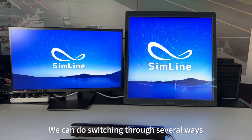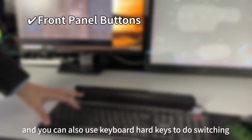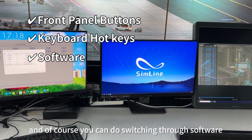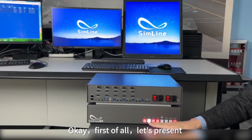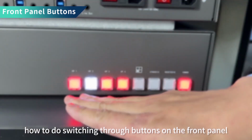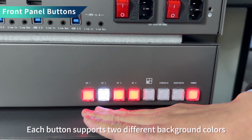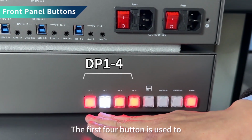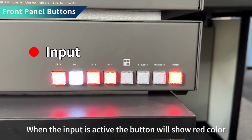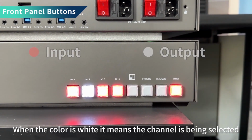We can do switching in several ways. The first one is by the buttons on the front panel. You can also use keyboard hotkeys to do switching. And of course, you can do switching through software. Okay, first of all, let's present how to do switching through buttons on the front panel. There are 8 buttons in total. Each button supports 2 different background colors. The first 4 buttons are used to select 4 different inputs. When the input is active, the button will show red. When the color is white, it means the channel is being selected.